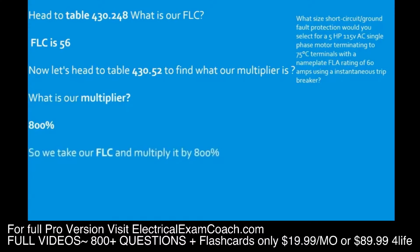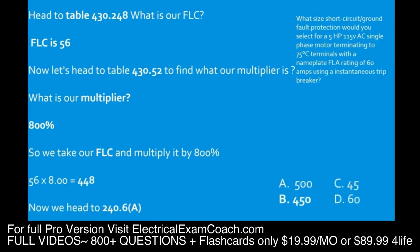So we take our FLC and multiply it by 800%. We take 56 multiplied by 8, and that's going to give us 448 amps to size our device by. Now we're going to head to table 240.6(A). We're going to select the next size up, and we're going to select a 450 amp overcurrent device.